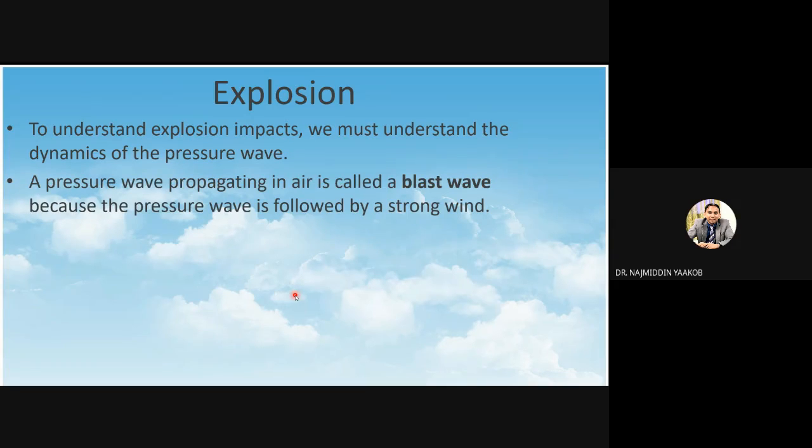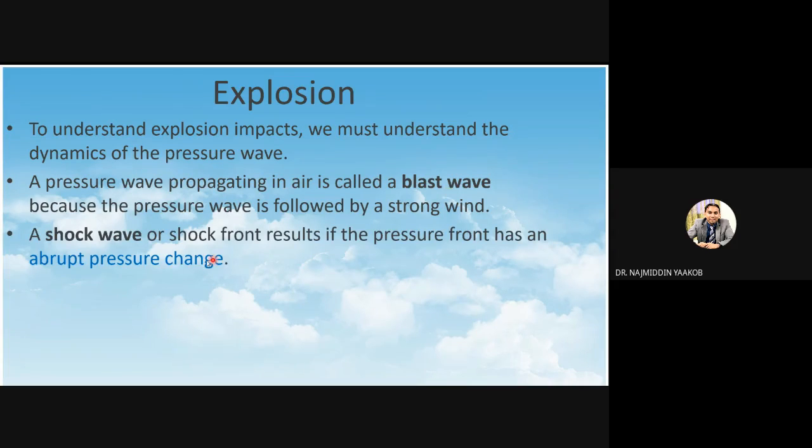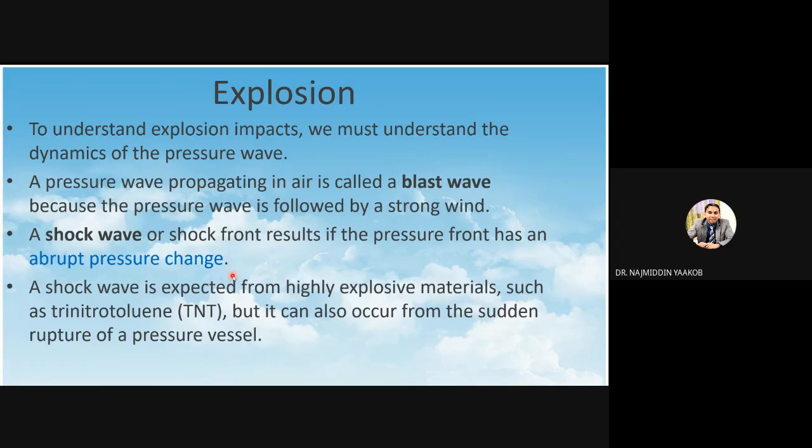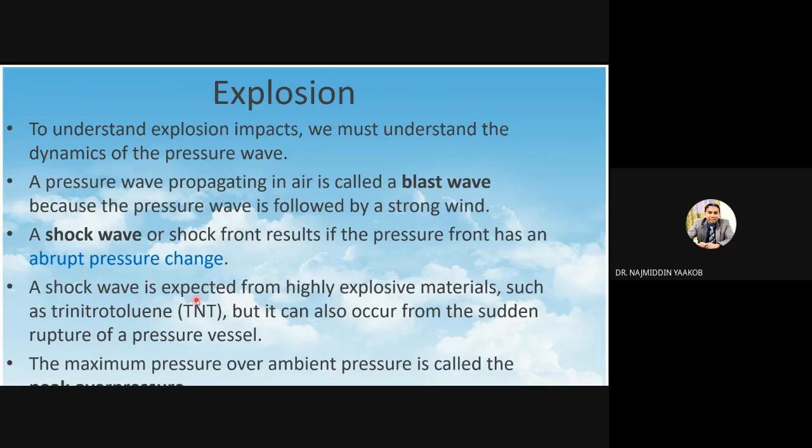To understand the explosion impact, you must understand the dynamics of the pressure wave. The pressure wave propagating in air is called the blast wave. A shock wave or shock front results in the pressure front having an abrupt pressure change. A shock wave is expected from highly explosive materials such as TNT, trinitrotoluene. Normally, this is a benchmark of an explosion. We benchmark the TNT. Okay. The maximum pressure over ambient pressure is called the peak overpressure. This is the comparison. Right.